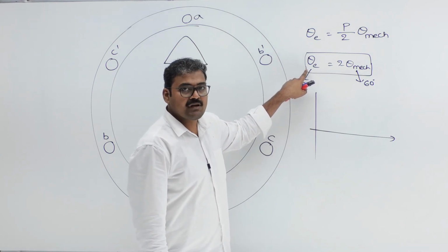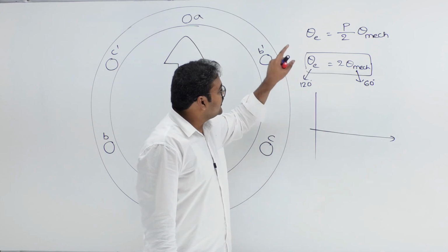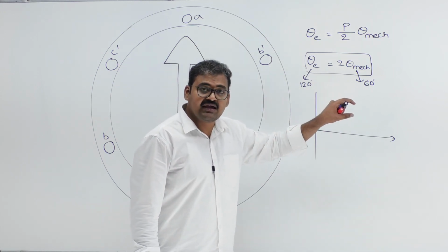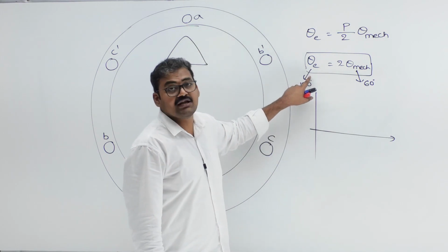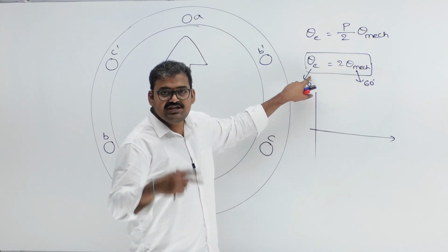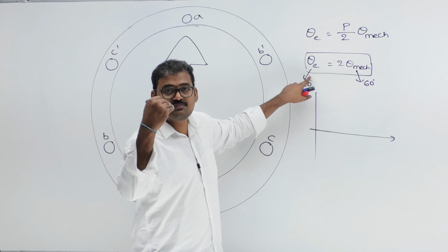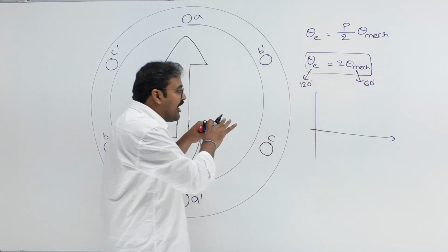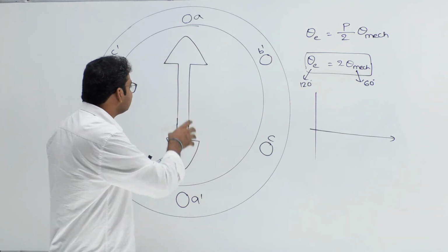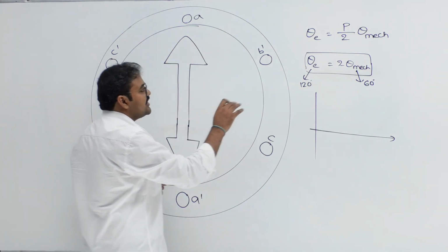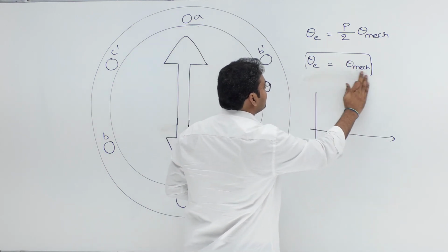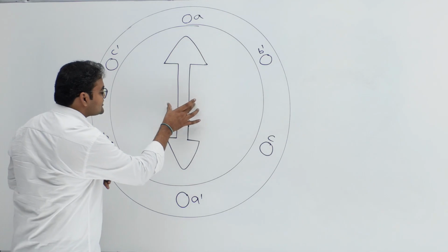Catching the point? So it is always very important to select the mechanical angle to satisfy the required electrical angle. 3-phase voltages must be displaced by 120 degrees electrical always. So to avoid that confusion, I am always selecting a 2-pole machine, because in a 2-pole machine electrical angle and mechanical angle are both the same. Alright. Now look at this rotor.